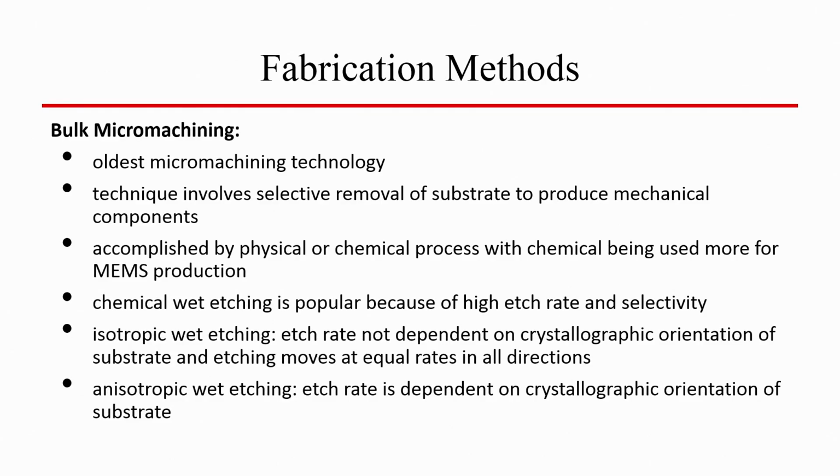So, if you want to understand further about micro machining, right, you machine everything, and machining is like if you have a substrate and you remove a part of the substrate. If you remove the part of the substrate, it is called machining. So, if you see the slide of fabrication methods, another very important step is bulk micro machining, and bulk micro machining is where you take out the bulk of the material.